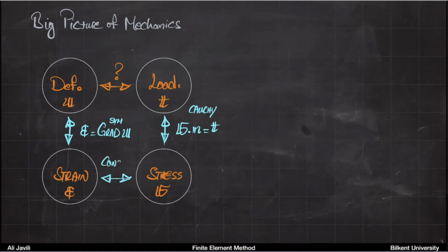So this constitutive law, for us, was sigma equals C epsilon. This is your constitutive tensor, that thing with 81 components, and usually we used the symmetry property of this, and we used Voigt notation, so you use this 6x6 matrix to identify that. But eventually this is Hooke's law.